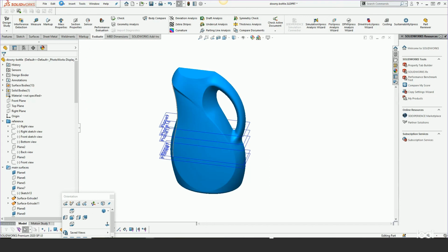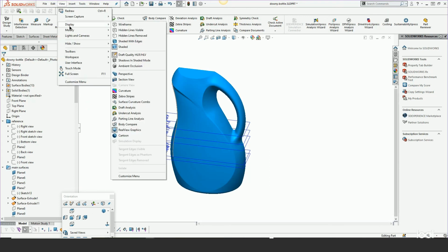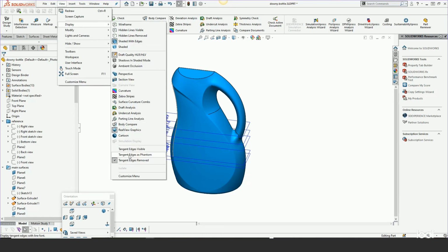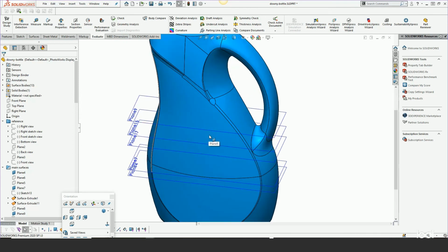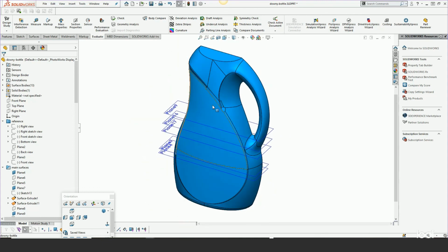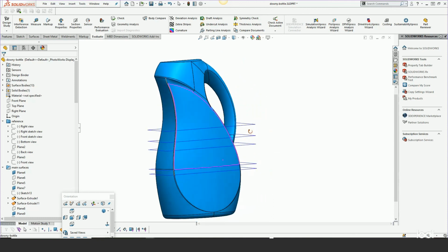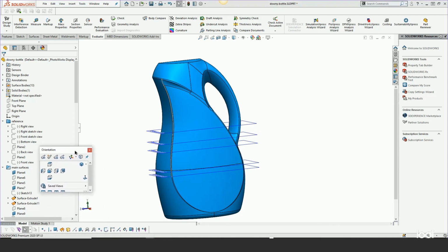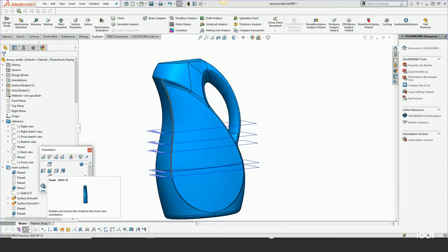And if we were to turn on or turn off our hide edge tangency, we'd be able to see that. So let's do that. So you can see it's made up of a patchwork of different surface types so that the overall form looks very continuous. And it's really the only way that I know how to do this. Actually, the better way to do this, but as a SolidWorks standard or pro or premium user, you're not able to.